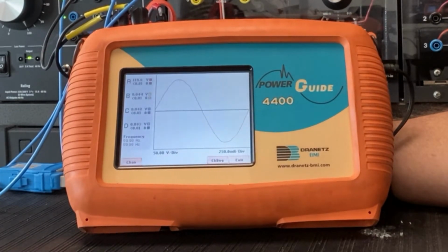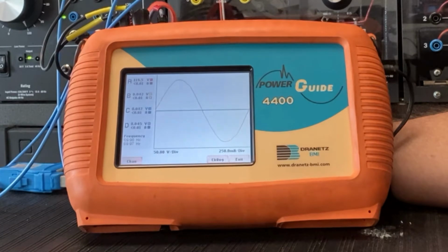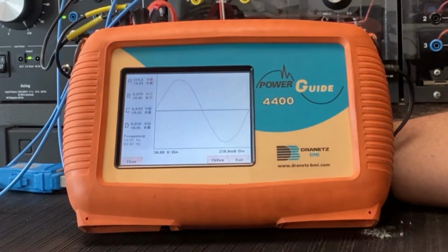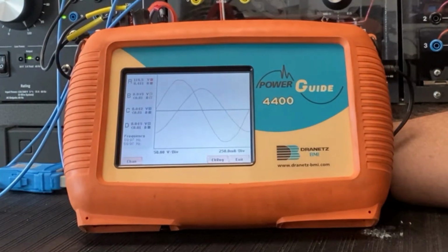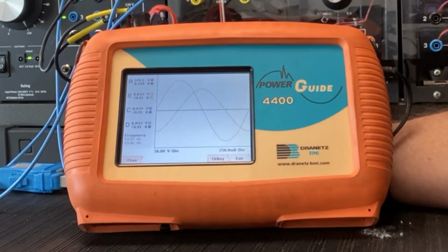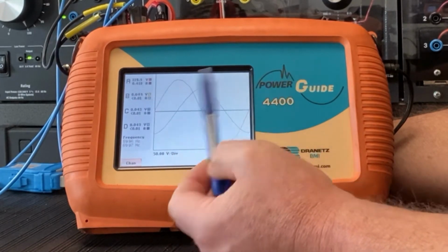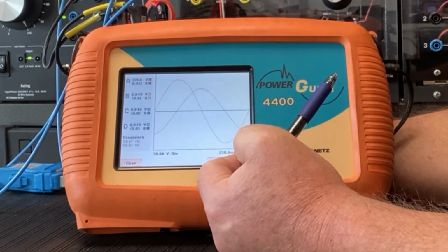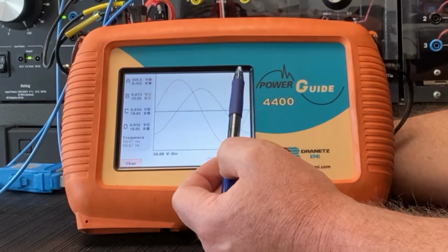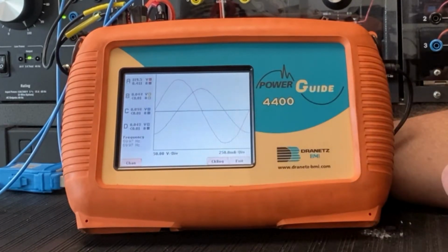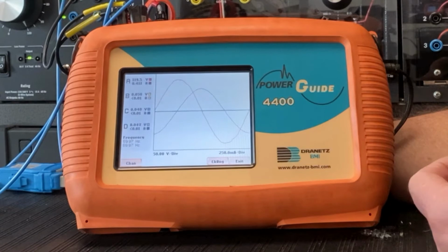Okay, so now I'm going to add some inductance to this circuit. And our acronym Eli tells us that with inductance the current lags the voltage. So I'm going to put in, what, 0.8 henries, which is about 300 ohms. And let's see what happens. The current should now lag the voltage. And look at that. Like I explained before, here's the voltage coming out, and it's peaking right here. But about 90 degrees off, the current is peaking. And it matches the graph that I drew.